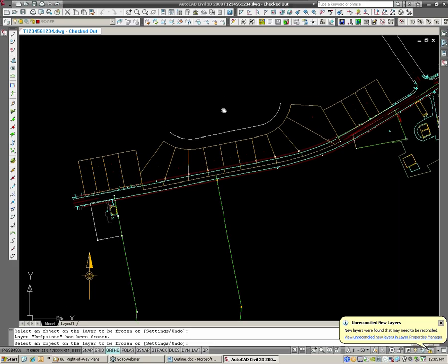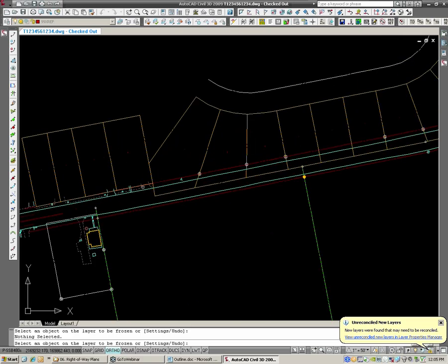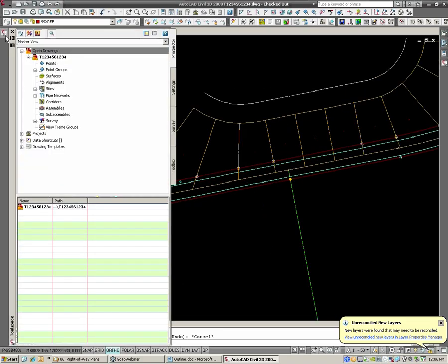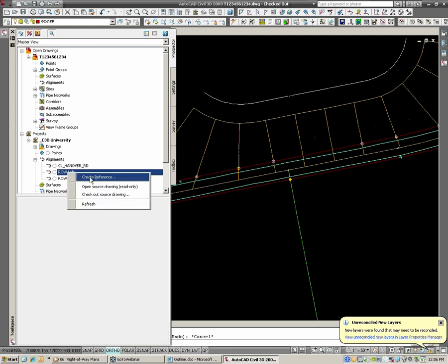And you can see somebody's gone ahead and created the existing conditions parcels for us already on the north line here. And this is where that right-of-way is going to jut into it. So let's take a look at what impacts we're going to have. So I'm going to go ahead and bring my data referenced alignment in and go back over to Prospector here, bring this down to Projects, go under my project itself, and I'm going to bring in that right-of-way line as a data reference.